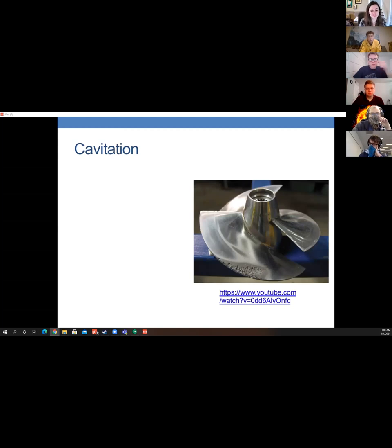I could give it a shot. Okay, Peter. So it's when you have a fluid flowing through a pipe and then the pressure gets really, really low and then you have little bubbles that start to form. Yes, little bubbles start to form when the pressure gets really low. Specifically, what threshold does it have to drop below in order for bubbles to form? The vapor pressure? The vapor pressure, okay? If the pressure of the liquid falls below its vapor pressure, it will start to form little bubbles.